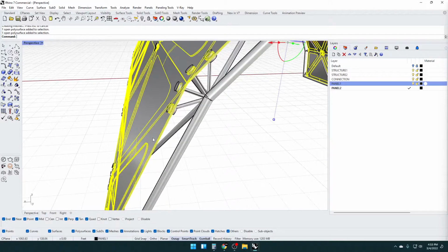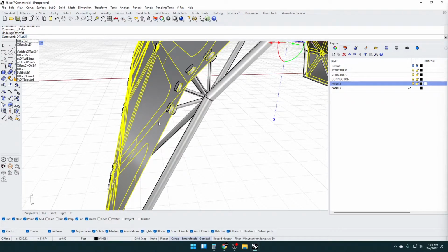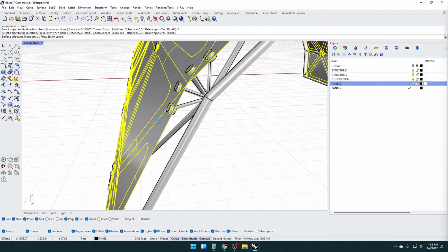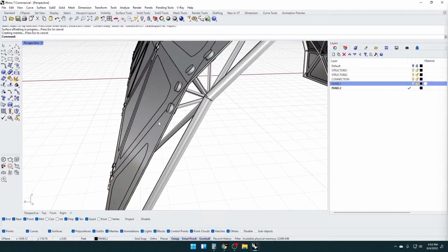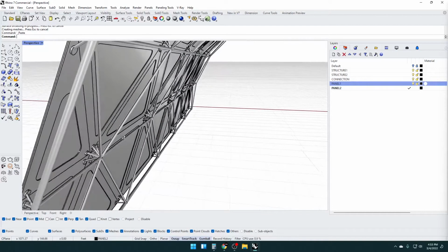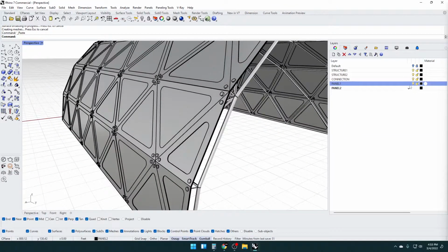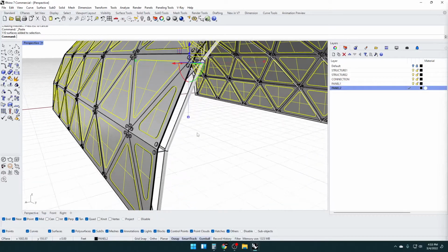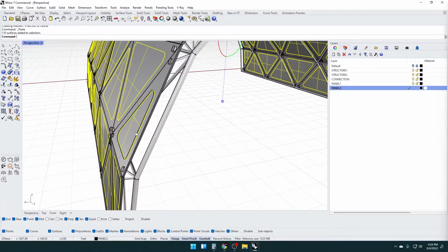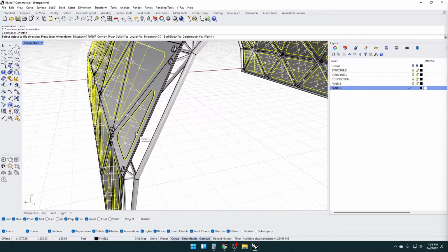Here's the thing, when you offset, it asks you if you want to delete the input. So I'll go here to copy to clipboard, I'll undo it, and this way I'll offset surface F for flip direction and do it again that amount. But this time, since I had copied it, I can now paste it because I had it on the clipboard. Now we have the outside panels, inside panels, and we'll go to panels 2, select objects, and do the same thing here. So we'll go to offset surface, we'll go to 1 inch, and we'll do less for the inside panels.